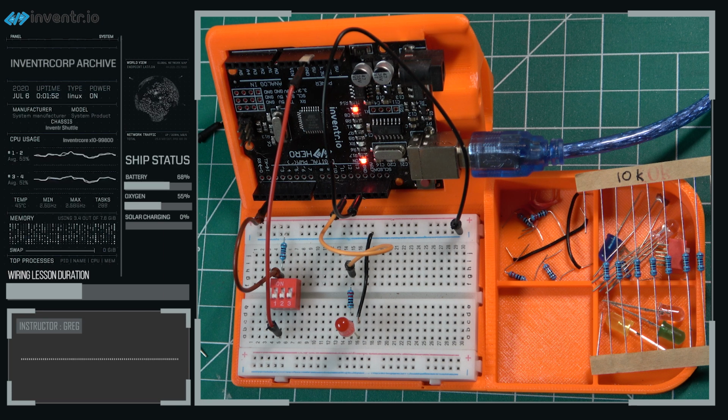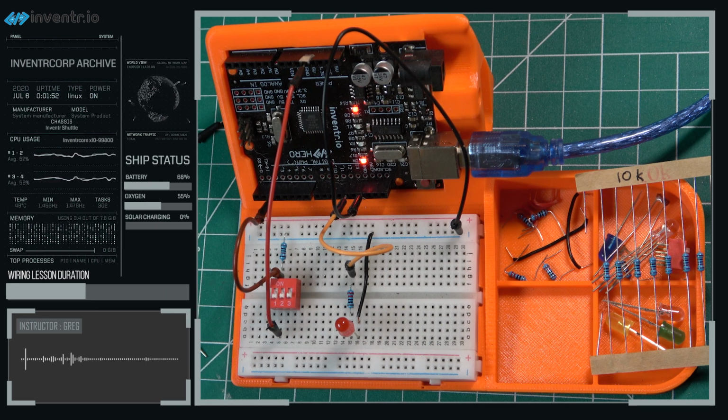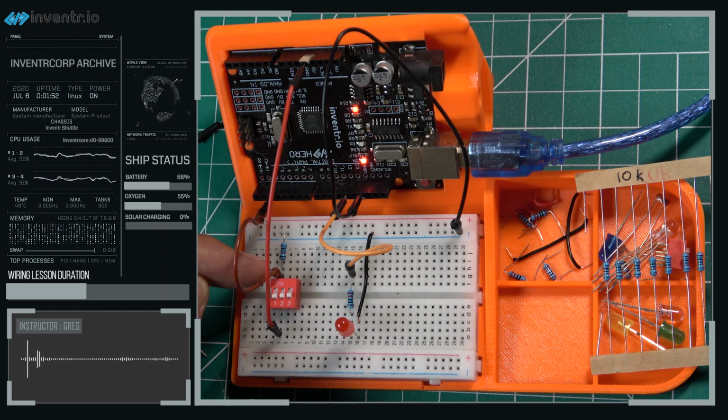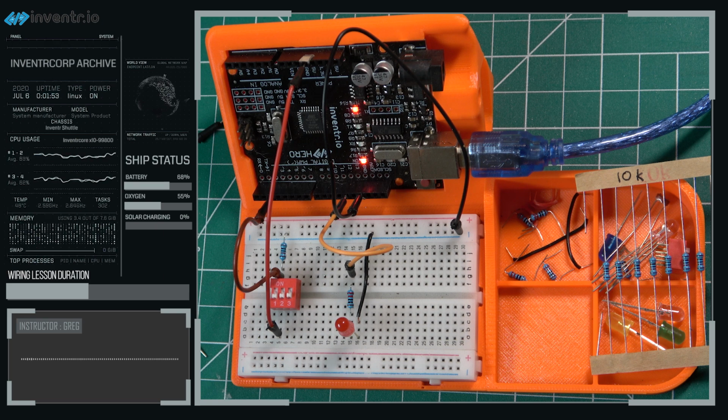On the other hand, if we were to throw this switch into the off position, breaking the circuit, then no current would be flowing through, and according to Ohm's law, there would be no voltage difference across the resistor between its ground side and its upper side. So both of those would be at 0 volts.